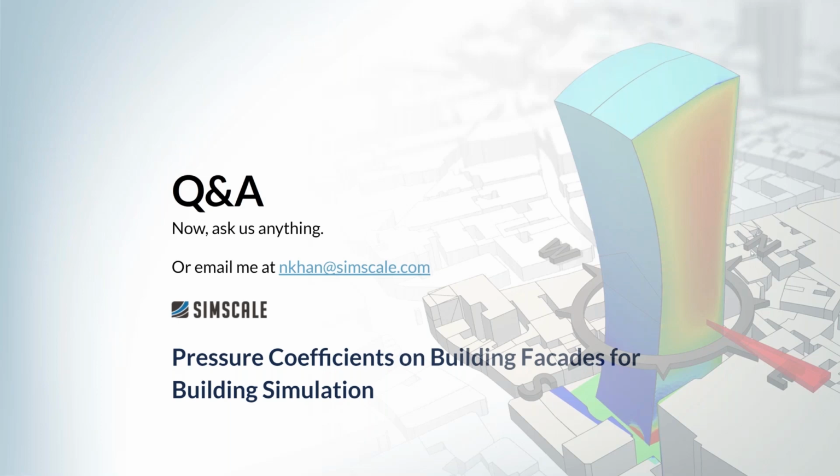So we've got this model. We can obviously analyze vortex shedding off of the rigid body. Obviously, some buildings will be influenced to some degree by that shedding and therefore make them wobble, but that is not taken into account. However, you can absolutely export slices that show the velocity slices, and you can see there the vortex is forming behind that building.